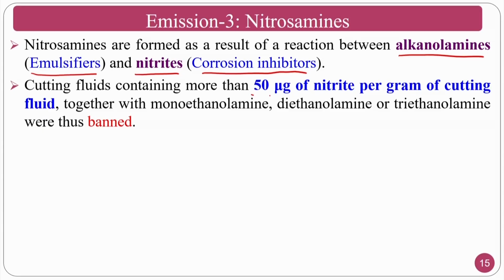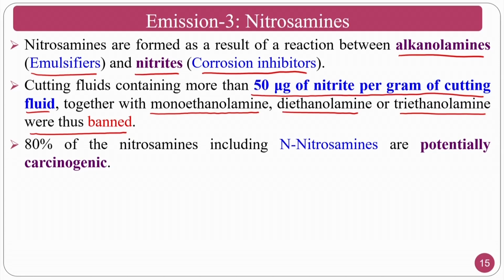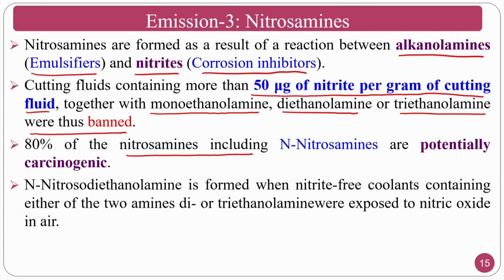Cutting fluids containing more than 50 micrograms of nitrite per gram of the cutting fluid, together with monoethanolamine, diethanolamine or triethanolamine, were banned. Eighty percent of nitrosamines, including N-nitrosamines, are potentially carcinogenic. That means these are very dangerous from the point of view of causing cancer.